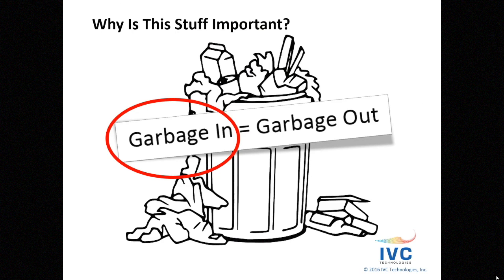Okay, why is this stuff important in the first place? And along with that, what's this garbage in, garbage out? Well, vibration analysis is a data-driven technology. So probably the most important thing is that I acquire good data. If I don't have good data, then everything that I'm going to be analyzing and making conclusions off of is going to end up being garbage. Hence, garbage in, garbage out. That's why so much of this stuff is important.